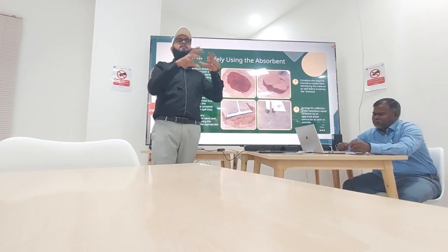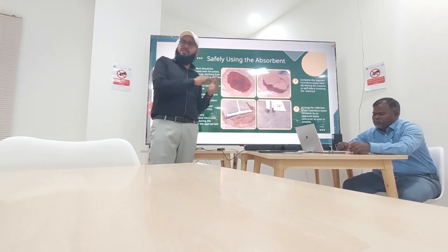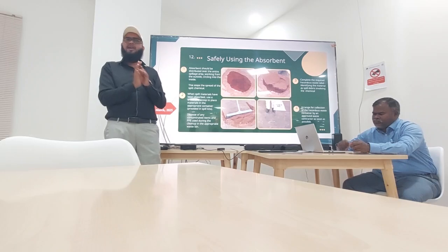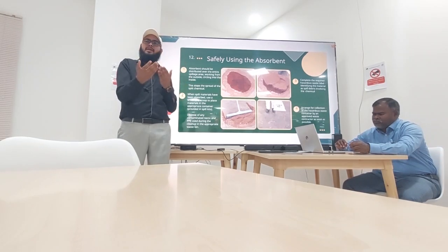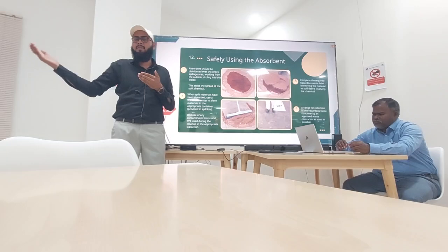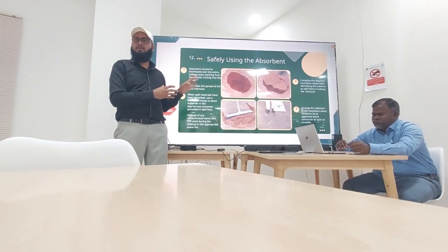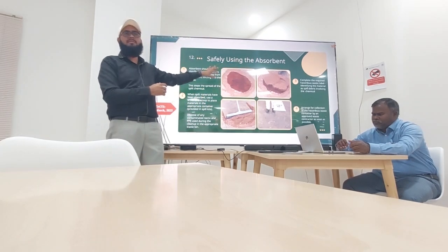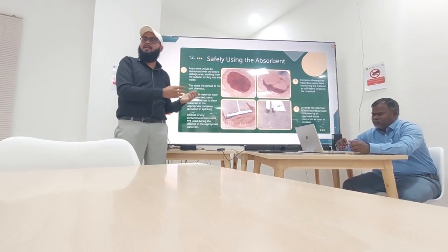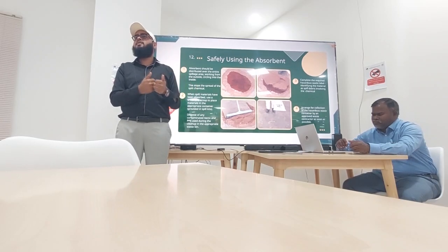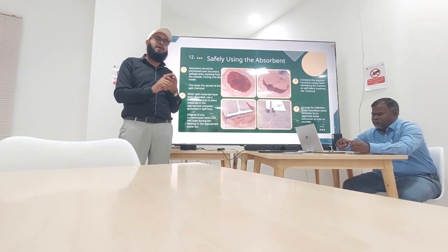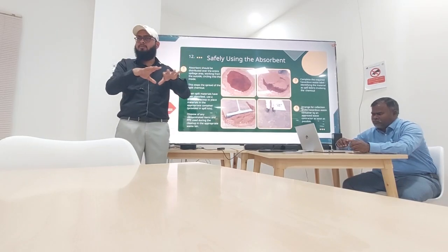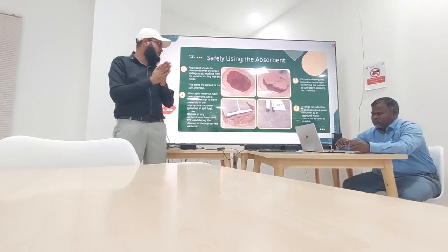After that, you can use any absorbent. Here we are generally not using soil. Why? If you use soil, it will further contaminate, and you would also have to deal with other things. But in case you can use it. Here you see someone has used soil. That's also one of the practices we use when dealing with a spillage. But here we have absorbents, especially socks, as well as socks for the fencing. Then we have pads to soak and cushions for both problems.